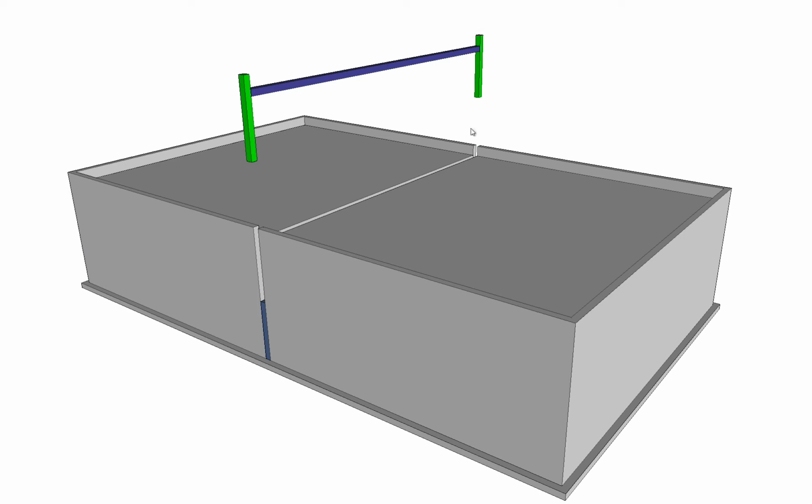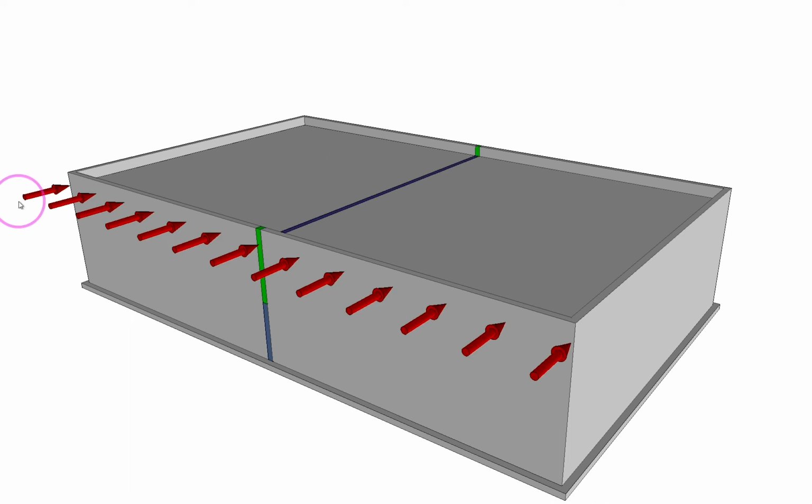And we're going to calculate weights of these two wall segments plus the weight of the roof. And a portion of that weight, a certain percentage based on our seismic calculation, will then become a lateral force that exists along the top, just the same way as it is with wind. And that wind load or seismic load gets transferred into the roof diaphragm, or if this is a multi-story structure,